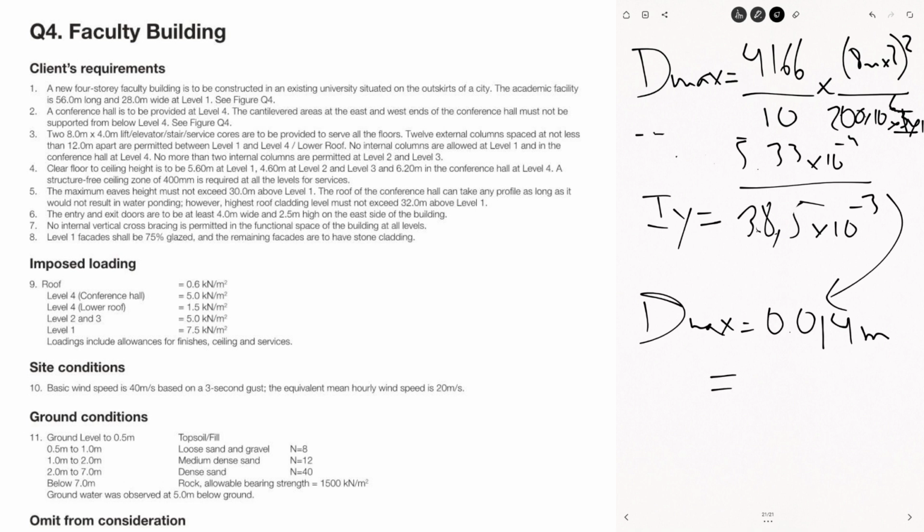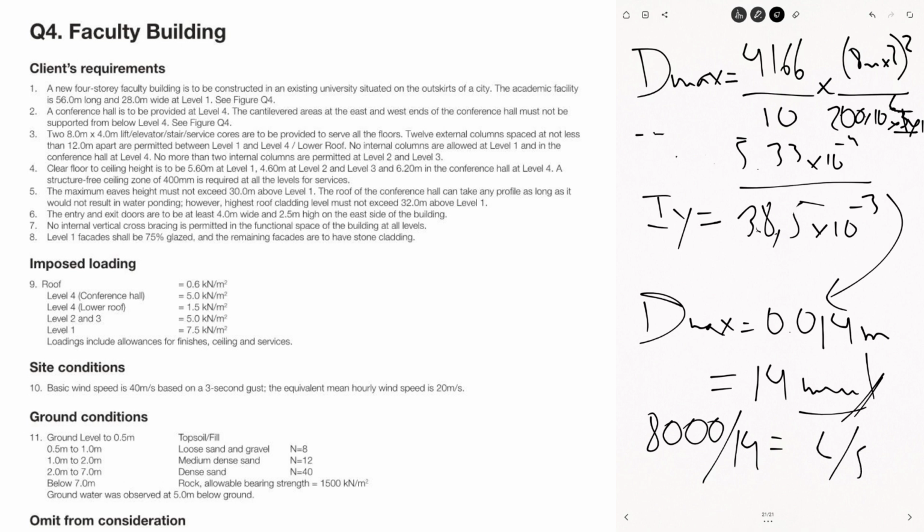So 14 millimeters, which over a span of 8 meters is L over 570, which is okay.